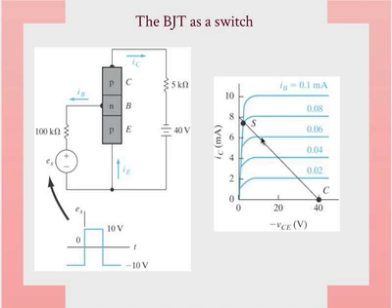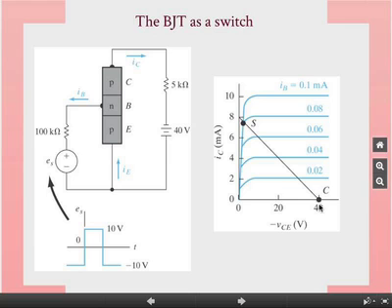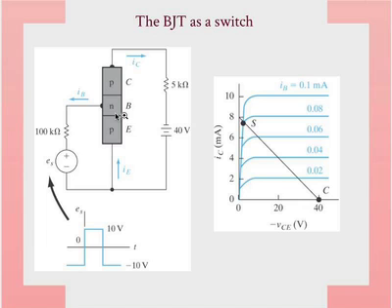Now, the key things to keep in mind are that we have what's called the load line, which we saw early on, which is of course determined by the load. You apply the output, which is out here. So you have 5 kiloohms and 40 volt bias. That determines this load line essentially. If the base current is very low, and you get the base current to be very low by applying a positive voltage in this case, you get that point C, where this curve is so small because this junction is reverse biased. This junction is reverse biased, so we essentially have a circuit where you have